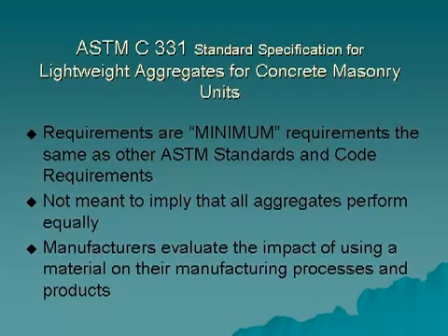It is important to remember that compliance with ASTM C331, the standard specification for lightweight aggregates for concrete masonry units, is verified by test reports. The test report should report that the aggregate meets all of the requirements contained therein, including the potential for drying shrinkage.